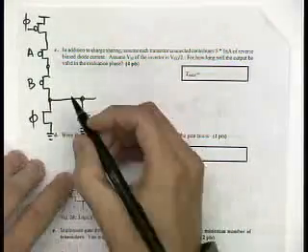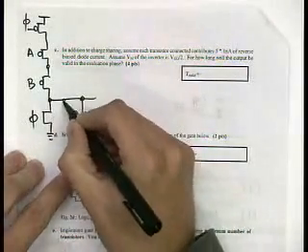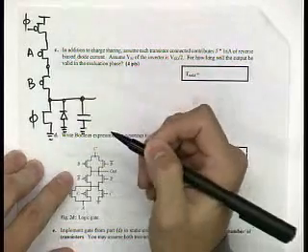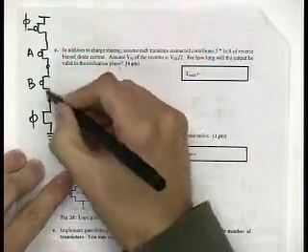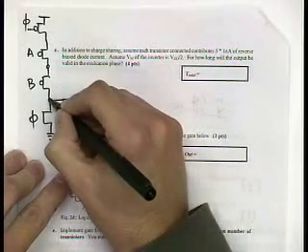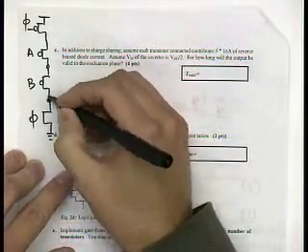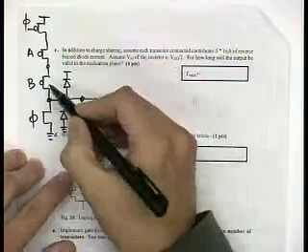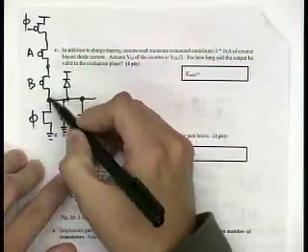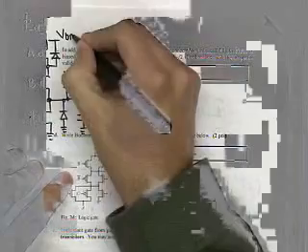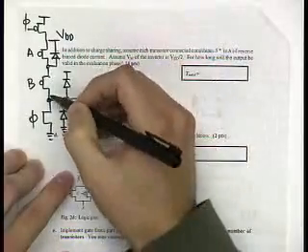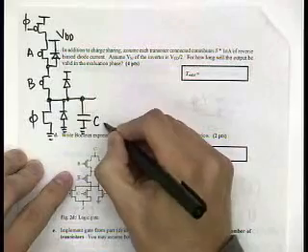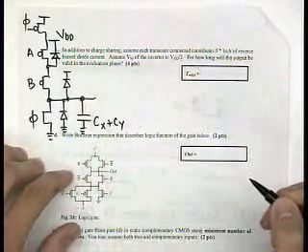So now you have to observe a couple things. So basically first there is a reverse bias diode over here, right, from the NMOS. There is another reverse bias diode from the drain region of this PMOS. So that's sitting over here. And since this transistor is turned on, then these two nodes are connected to each other. So there is another diode from this guy. And since these two nodes are the same potential, then the total capacitance is equal to Cx plus Cy.